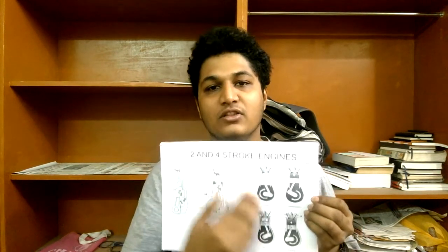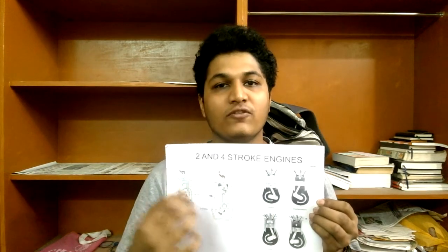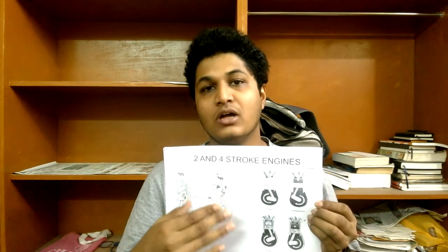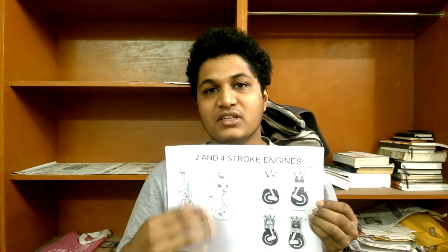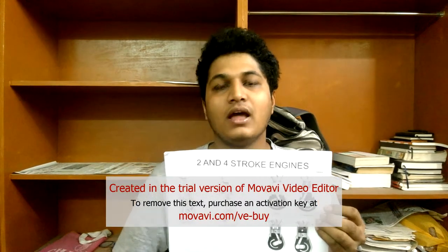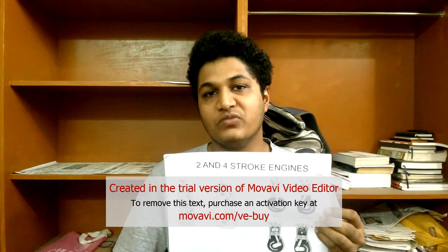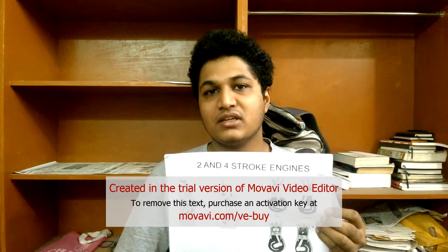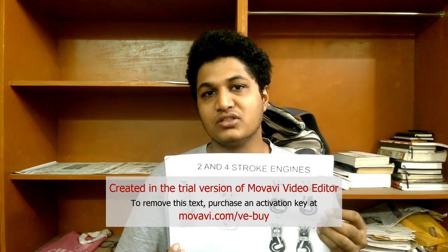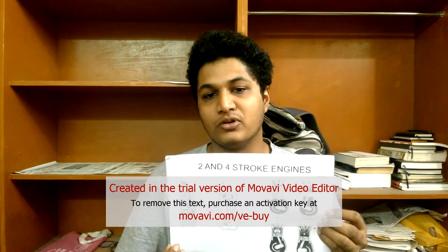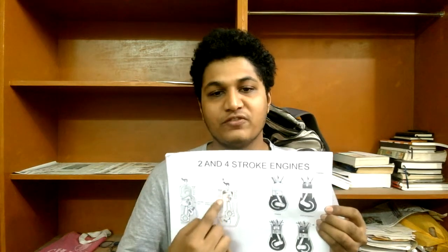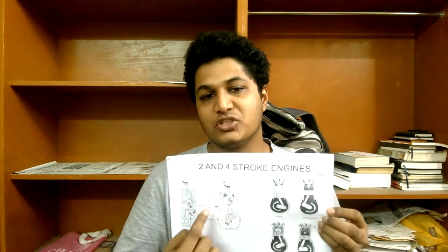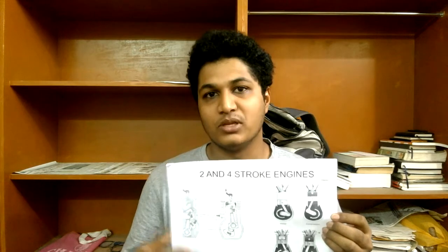In comparison, the four-stroke engine needs four strokes for a single cycle to be completed, which means that the piston needs to go upwards twice and downwards twice before one cycle is completed. As you can see, the two-stroke engine can obviously complete a single cycle faster than a four-stroke engine. This means that for a given mass, the two-stroke engine can produce a higher power output. But at the same time, because of its inlet and outlet design, it will be less efficient, which is why a four-stroke engine is normally preferred.